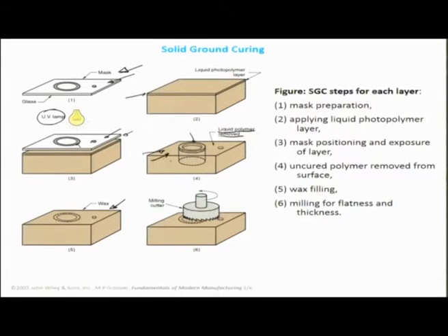So when you're coating this 3D feature which has been formulated on the top of the surface here with wax, the wax kind of embeds. Look at how this feature is getting embedded. The lines here are dotted, which shows that it's a hidden layer. Okay, and the wax formulates a layer on the top. We can actually have a micromilling cutter which removes the wax to a sufficient extent so that it just starts exposing the small solid layer. Okay, maybe machining a few mils of the surface, which probably gets the system ready for the second step of exposure.